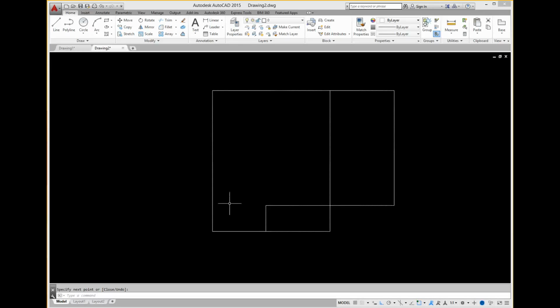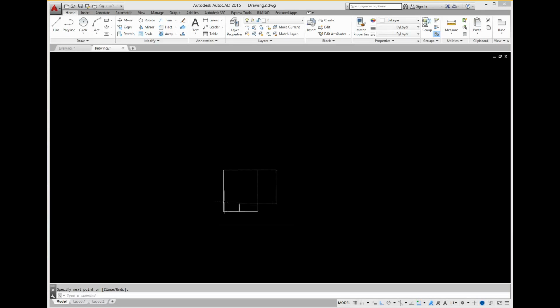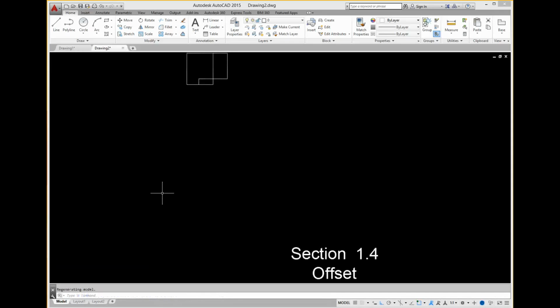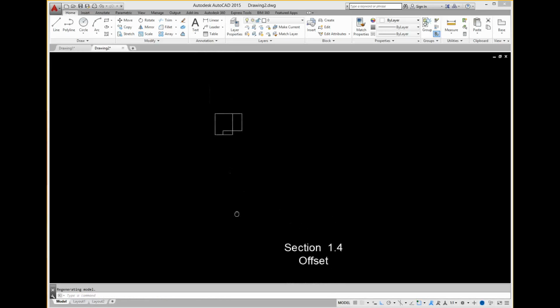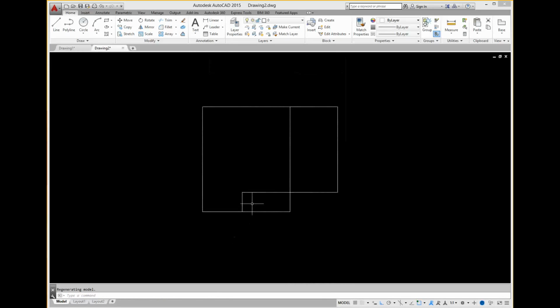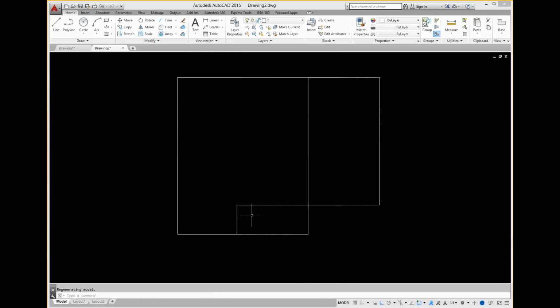So once again, let's look at the zoom command that I was talking about. It didn't work real well the first time. Sometimes AutoCAD gets glitchy and it doesn't do what you tell it to do. But let's type Z and enter, and then you'll see in the command line we get a lot of zoom options. If I type now A enter, you get the whole drawing coming up and filling up the screen.